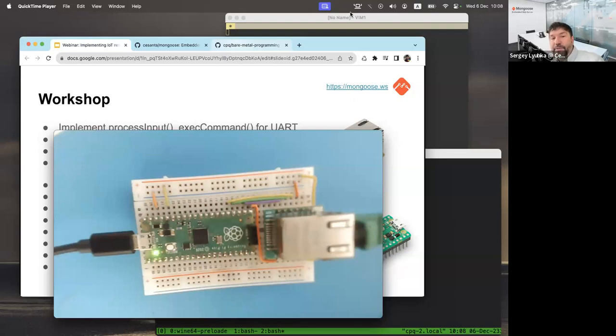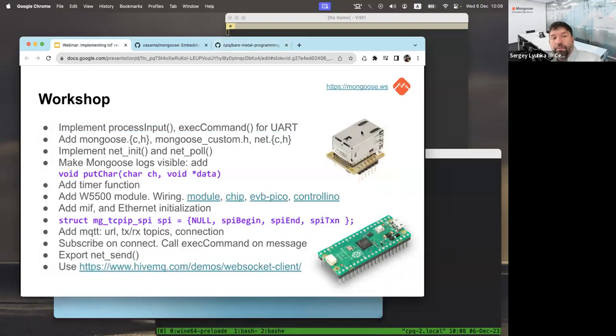And by the way, everything that I'm going to show here would apply to pretty much any other microcontroller, because this specific Ethernet module from Wiznet provides an easy-to-use serial SPI interface to read and write Ethernet frames from the network. That means any microcontroller with an SPI interface is able to use that module, and so is able to receive and send Ethernet frames.